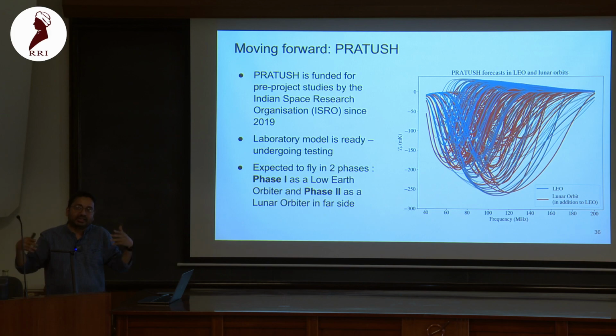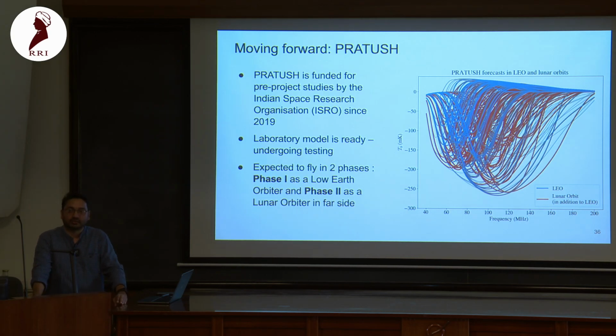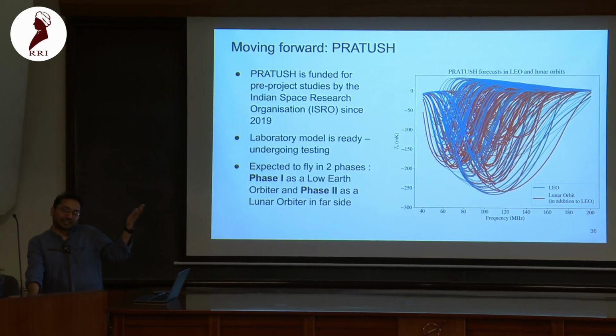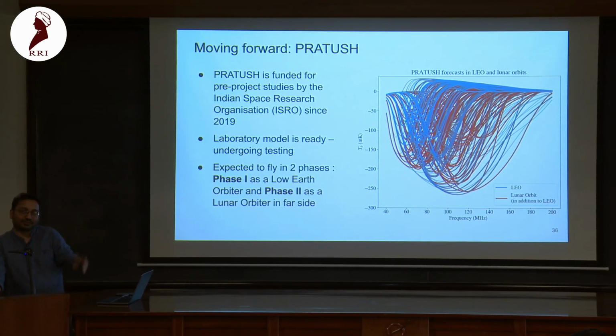With dipoles it's possible, but dipoles have other problems, like the balun, for example, which are an issue for us. Also, if your dipole is at a height, you have another length scale in the problem, from your feeding point to the ground. That can also produce standing waves, which is what was seen in SARAS 1. That led us to transition from a dipole to a monopole. So having a beam which is off zenith is not an ideal characteristic, but that's what we have to live with.